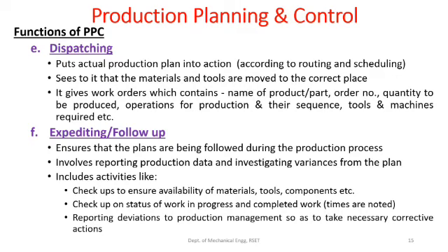So dispatching ensures that the materials and tools are moved to the correct location or correct work center at the correct time, and this is done through work orders. Now the work order contains the name of the product or the part that needs to be produced, the order number, the quantity to be produced, the operations for production, their sequence, the tools, machines required, etc.